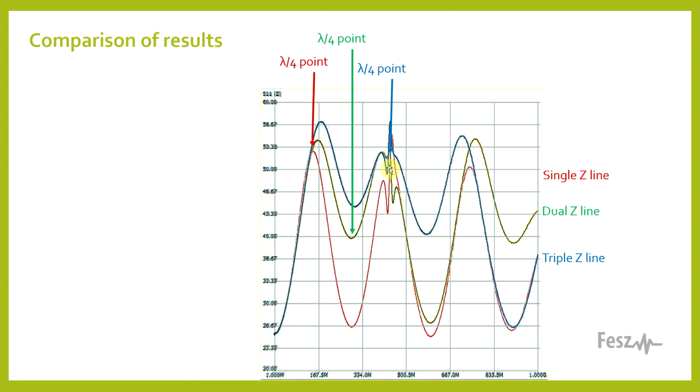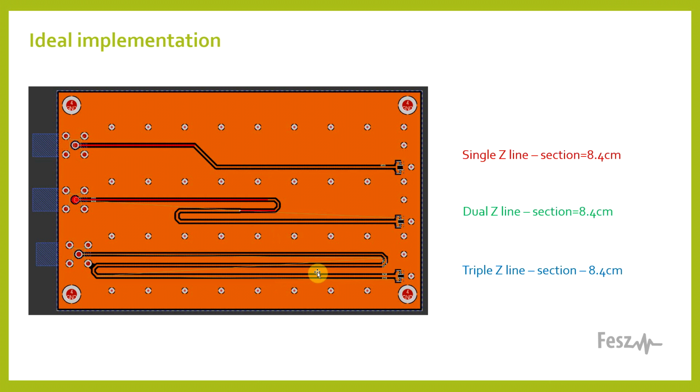And this does highlight an interesting problem though. The more sections that you add, the larger the matching transformer becomes. So even though you might want a 10-section very wideband device, it might just be a bit too large to actually be practical.